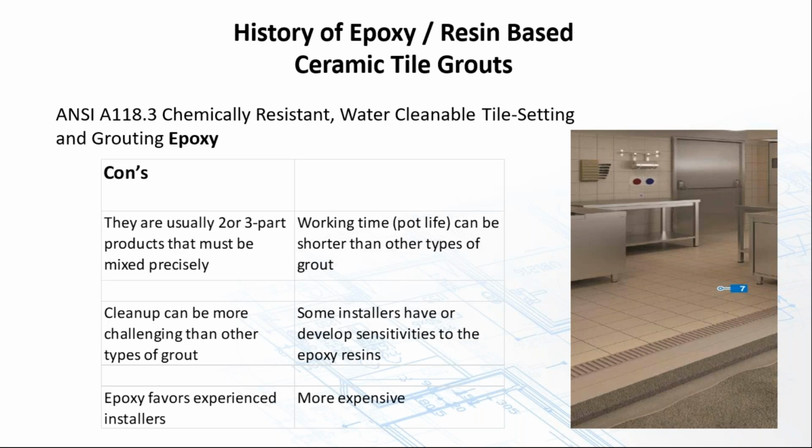The other thing to keep in mind is the curing times on these epoxy grouts. So if you're doing a commercial kitchen and you're trying to do a repair in it, the fact is that we do need the curing time on it to be covered and protecting it. I've often been asked, can't you get an epoxy that can set up quicker so we can get these repairs done and we have less downtime on the kitchen?